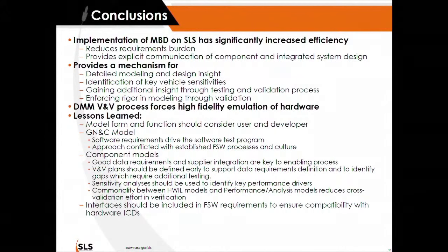use the right model where you need it. For example, if you're doing software testing, your model needs to include the interface to a high level of detail. Whereas if you're doing performance-based analysis, that might not be as important, but it's more important to match the error statistics and the behavior of it. So knowing what model to put where makes the most sense. For example, an interface model might not go well in a 6-DOF Monte Carlo sim, where we don't care about a bus interface. We can model that at a higher level.